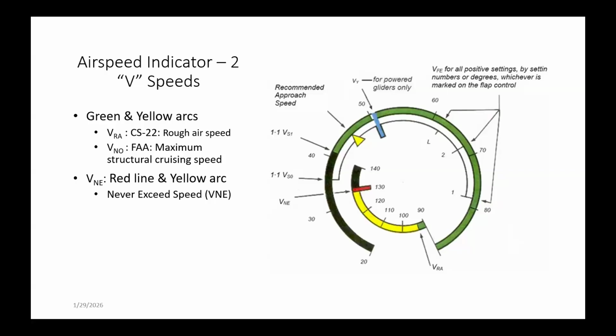So if we're talking 3,000 meters, I'm just rounding here, I'm not looking at a number, 10,000 feet, then if you're above that, in this case where it's showing the red line at 130 knots, let's say you're bombing along around 14,000 feet, your red line probably isn't 130 knots now.